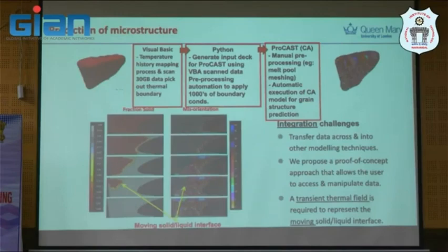A good question from the previous audience. They're asking about nucleation condition. We assume a normal distribution at the melt pool boundary at this time. But it's a valid assumption, because the parent material actually is quite uniform, it's a rolled microstructure, so it's quite uniform after homogenization. So average grain size is kind of known for high standard aerospace application. So it's kind of a valid assumption to make. I believe it's a 30 micron grain size at the rolled parent material.